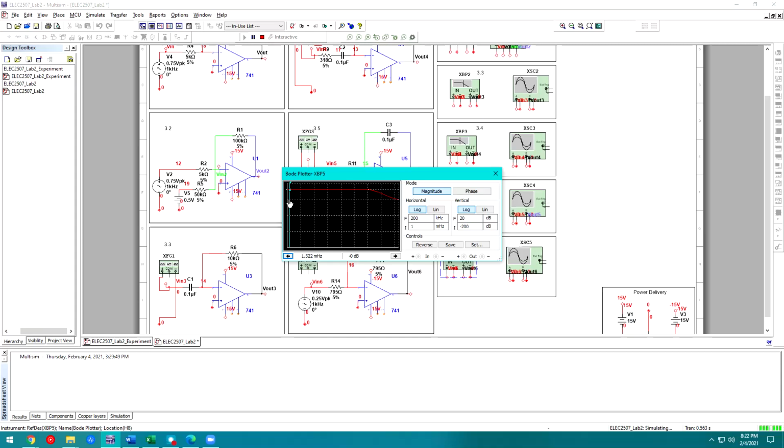So during most of the passband from 1 millihertz to about 15 hertz, it actually is 0. So we're having absolutely unity gain in the circuit. This is just acting as a buffer, the circuit, up until the 3 dB point of 2.12 kilohertz, and then it is attenuating all the signals above that, right?